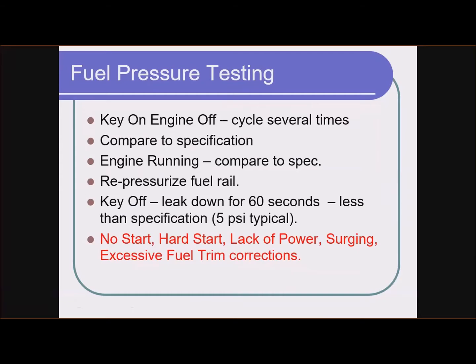Other vehicles have not included the fuel pressure test port, and so we can't just screw a gauge on. We have to somehow tee into the line. That can be a little more challenging. You need a lot more adapters and things like that, because of all the different types of quick connect fittings that are on fuel rails and fuel lines and fuel filters, sometimes you have to almost make something up. So we'll assume that we have managed to configure a fuel pressure gauge to measure the fuel pressure on your vehicle.